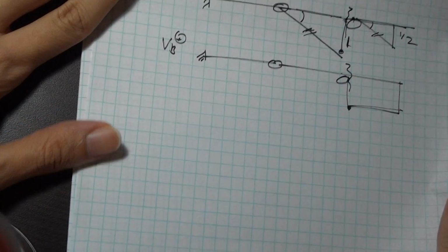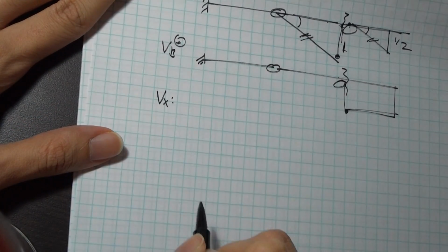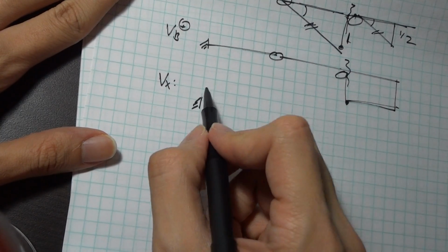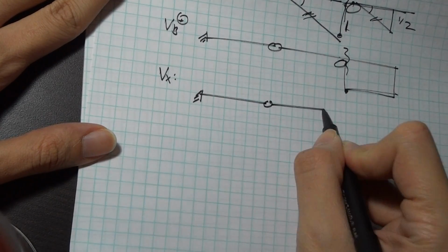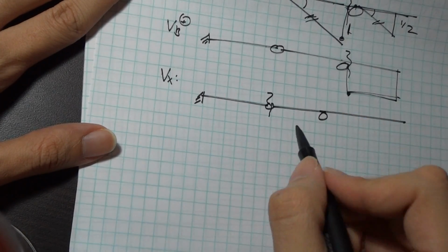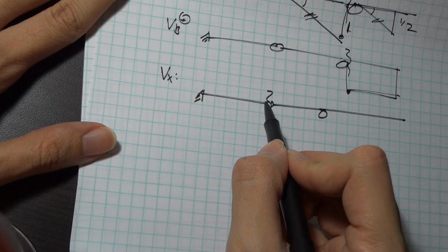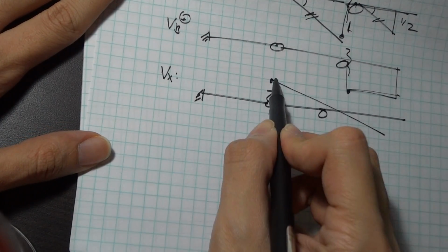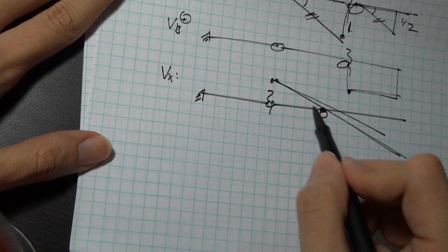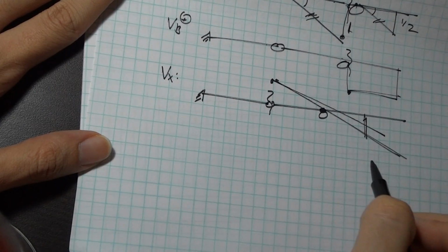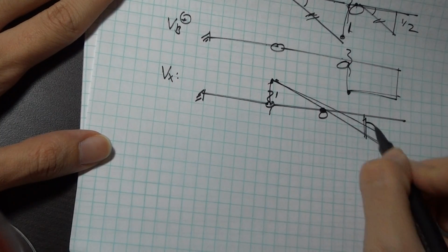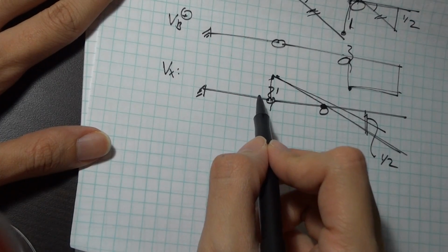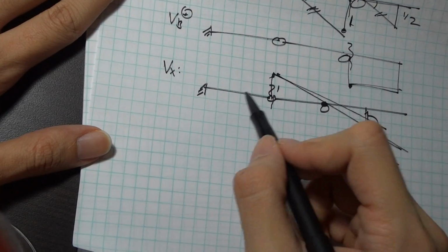The last one is the shear at X. And in this case it doesn't matter, X is the hinge. I don't need to look at left or right, it will have the same result either way. I'm cutting it here. This one cannot rotate, therefore this deflection will remain 0. I'm going to lift this point up by 1. It's going to pass through this point, and I'm going to get a diagram that looks something like this. So you can see here this is 1, and again this will be 1/2. I'll have 0 here, and this is one of those cases where they will not be parallel.